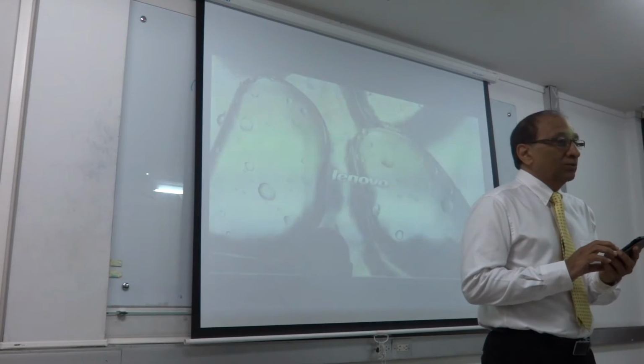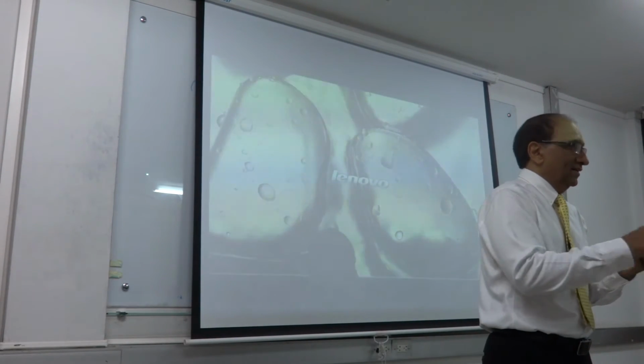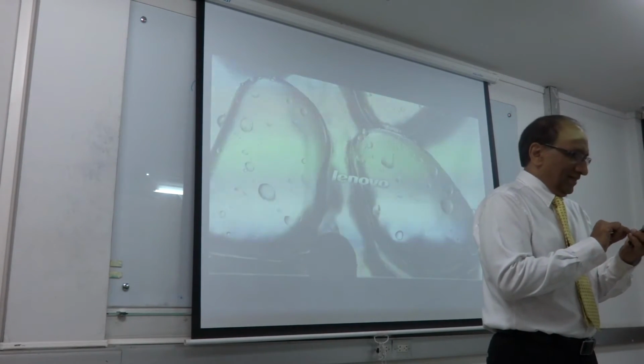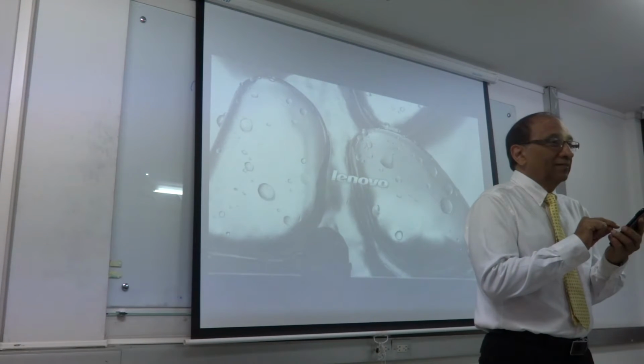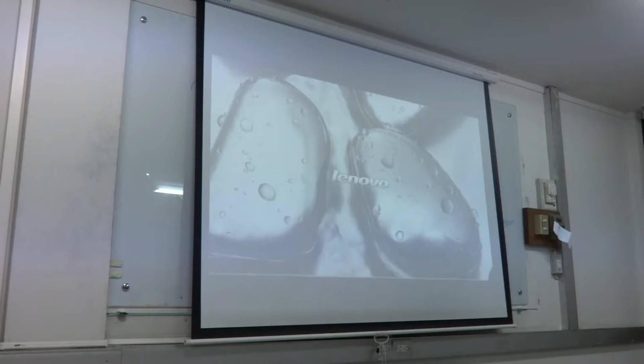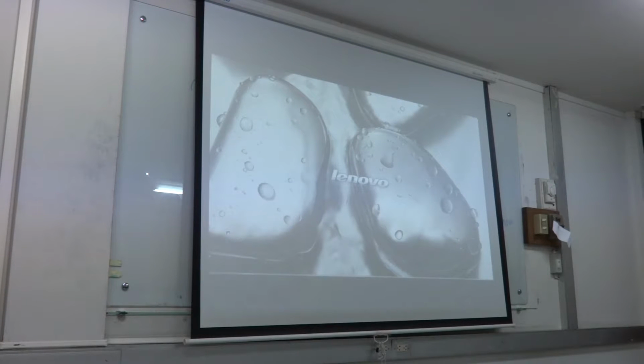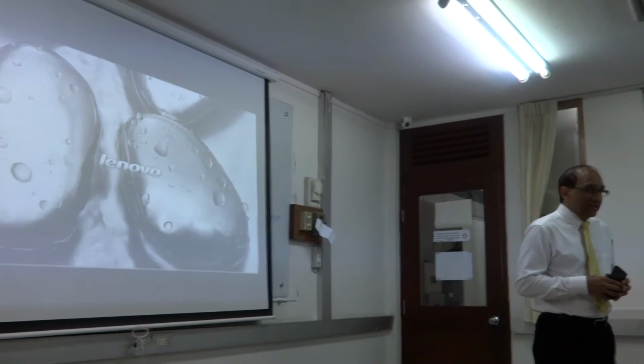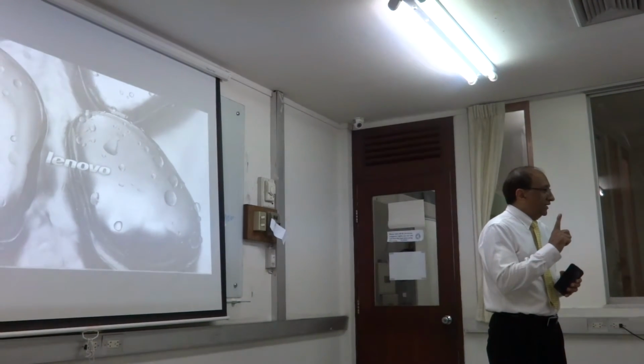So if the torsion is, let's say, the capacity of the beam in torsion is 1 ton meter, and your torsion is 0.4 ton meter, nothing to do. If it is more than 0.5 ton meter, minimum reinforcement. More than 1 ton meter, all of the torsion must be taken by steel. And similarly, we have the same limits side by side like shear. And finally, you calculate the reinforcement for torsion, from shear, put them together.